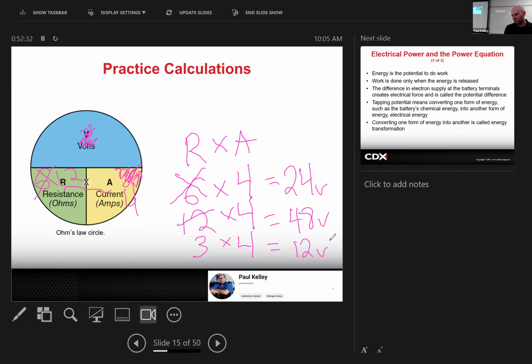So there's actually been pretty good discussion about, hey, why don't we increase the voltage in the automotive system? There's a little bit of challenges with that. I mean, 12 volts is really safe. We've spent 100 years fine-tuning electronics for 12 volts. So 12 volts is just what it is. It used to be 6 volts back in the day, but you can see there is some logic for why you would want to potentially increase the voltage. And when we do power calculations, I'll show you one more really good reason we may want to.